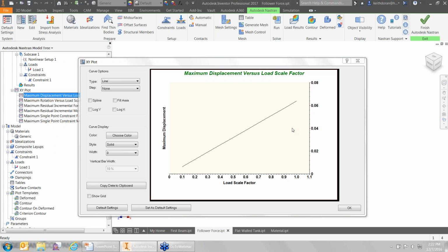Later on, I'll take a look at another simulation where we'll definitely get different displacements based on the load, or a magnitude of displacement not linearly applied to the load. Okay? So the stress and the strain are not linearly functioning. And this is kind of important, right? Because sometimes we don't need a nonlinear analysis, and this is telling us right away that we just went through the nonlinear function and the linear would have worked just fine, right? It would have output the same information.